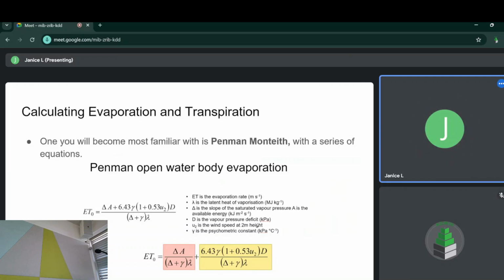On the other hand, you have another concept known as actual evaporation or evapotranspiration, the variable ETA, and that is the actual amount of water that is evaporated into the air. If you had 1 liter of water in a bucket outside, no matter how hot the temperature gets, you cannot evaporate any more than 1 liter of water. There is only 1 liter in the bucket to evaporate. And that's the difference between actual evaporation and evapotranspiration, and potential evaporation and evapotranspiration.